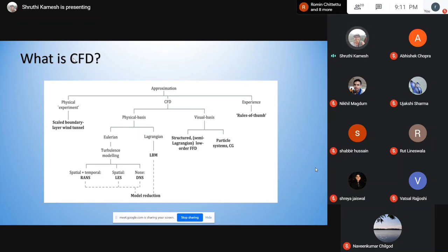When you have a mean part, you can say that on average, my fluid moves through these particular locations. You cannot be very specific, but you can say that on average, it moves in a particular way. Any fluctuations, that is, any eccentricities in any particular direction, are what the fluctuating part accounts for.